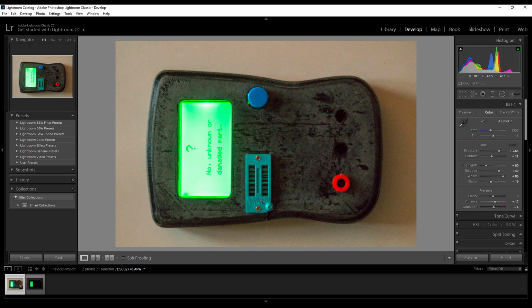Now, we've talked about using Maya for this kind of thing and what it's good at. Let's have a look at what it's bad at, because in a test print like this, I can see here around the corners we had too much support edge geometry, which is why we've got this sort of ear effect here. And we need to change this. Also, there's too much plastic up here, so I want to round these corners off.